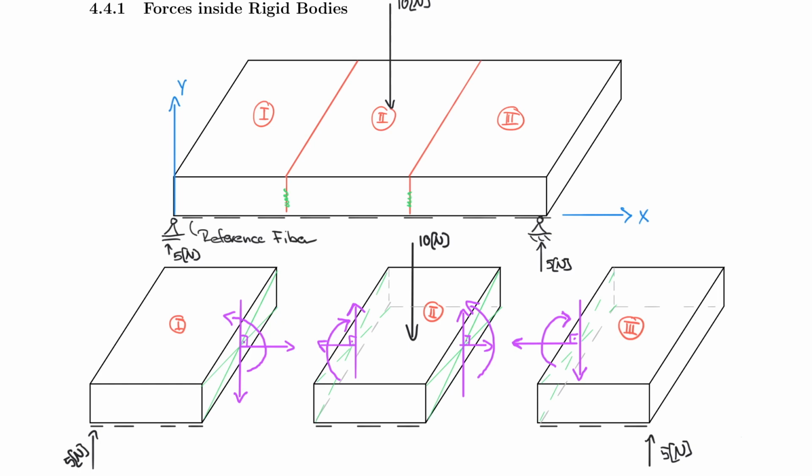So now you know that we have always on these surfaces 3 forces, the shear force, the normal force, and the moment, and that they always have to be in balance with the other side, with the opposite side. Otherwise, the system would not be in equilibrium, and then the glue would not hold it statically together, right? So this glue line here makes sure that element 1 and element 2 are together in equilibrium. And that equilibrium is just shown symbolically here.